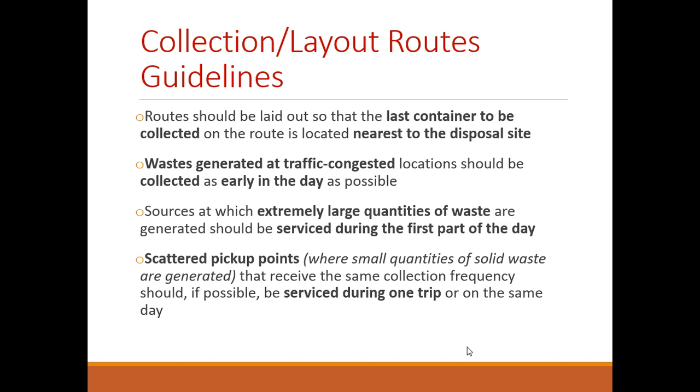Then we also have scattered pickup points. This is where, for example, small quantities of solid waste are generated. These scattered pickup points that receive the same collection frequency should, if possible, be serviced during one trip or on the same day. If the frequency of collection is twice for the week, you want to make sure that on that one trip, where possible, you could service all those scattered pickup points.